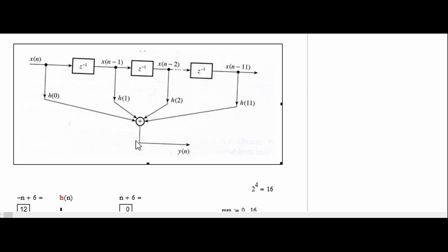So if we look at the structure, you now realize that this filter, although it's a real-time filter, meaning when it's running it will run, the first few steps of it won't be a stable filter. If you switch on this machine for the first time, these values will probably be 0, meaning your filter is not going to work in the beginning. So you have to wait until these shift registers are full before it will process as a real-time processor, if that makes sense.